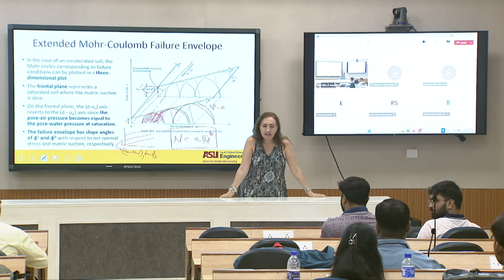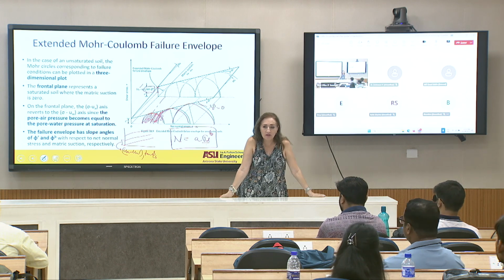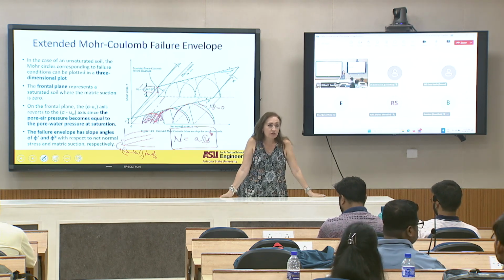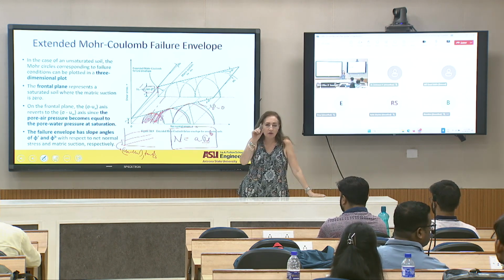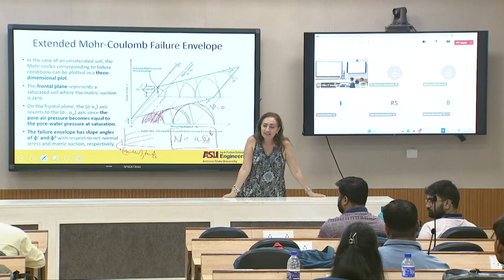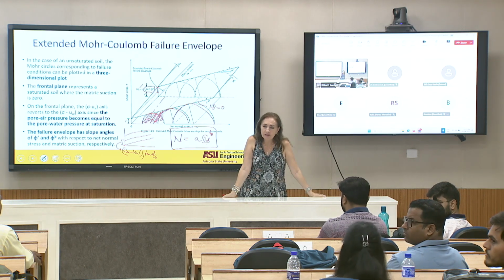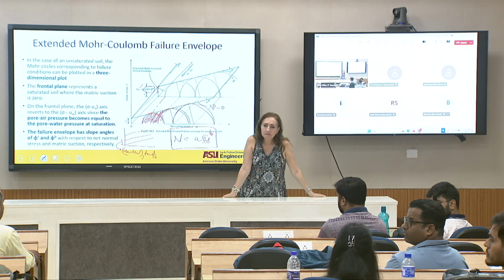There are some models for permanent deformation of soil, and they also account for confining pressure and consolidation. Do you have that, Rahul? I'm not a pavement expert, but the first part takes a power law form, and then the second part is exponential, the secondary compaction where the deformation is very high.